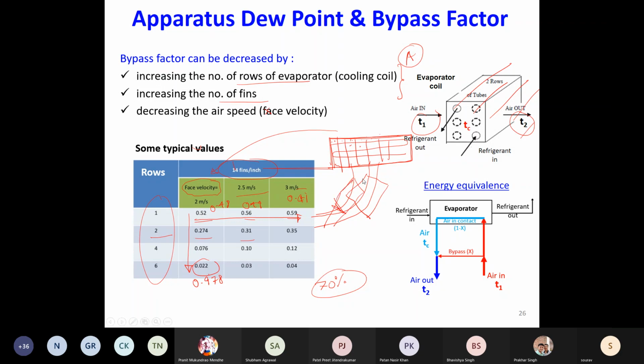So it's in the form of a triangular shape if you look at it from the side. Most of the heat exchangers, you will see, consist of only 2 or maximum 3 rows you may find. Going to 6 rows is not practically desirable from the fan power point of view. Any questions?